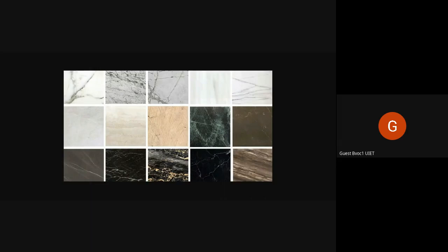It can be polished very nicely, and it is available in a lot of different colors, and it is soft and easy to work. It is used in flooring, for cladding, staircases, and ornamental works, for sculptures, and it can easily be carved. And it is found most commonly in India, in Rajasthan, Maharashtra, Gujarat, Andhra Pradesh, Mysore, MP, and UP.